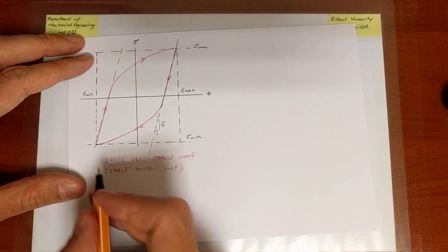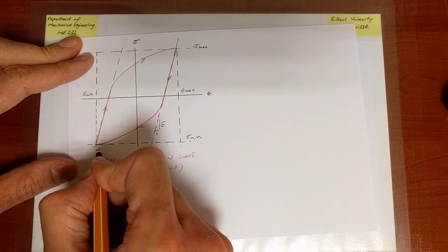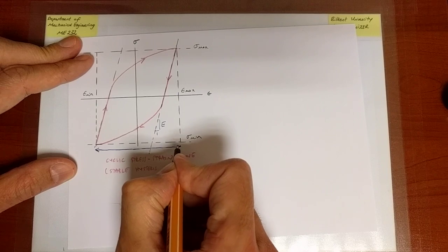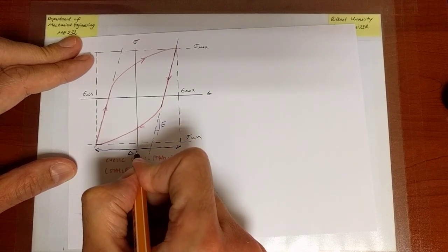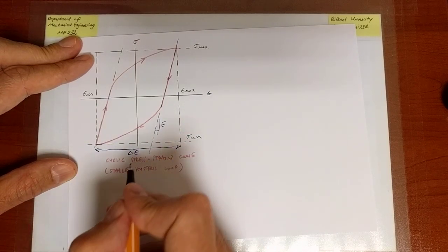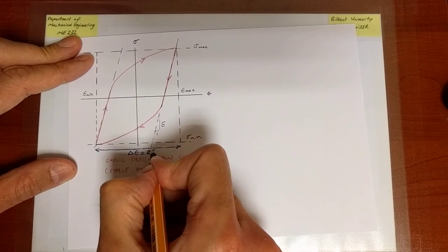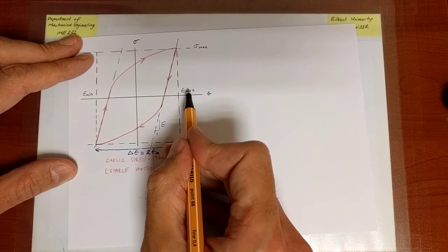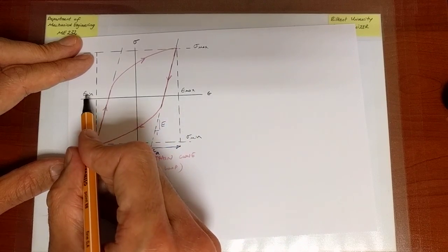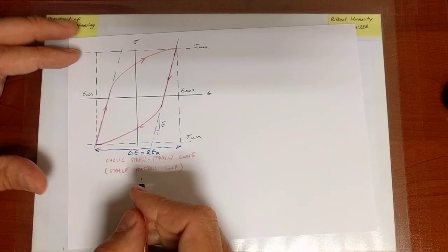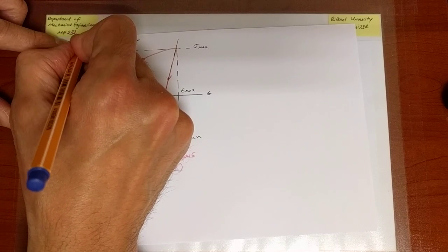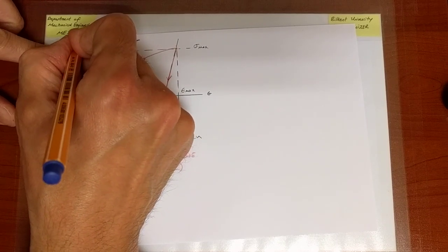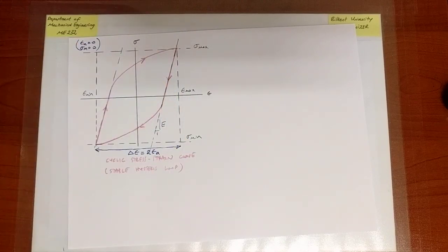So first of all, the strain goes between some max value and mean value. So therefore, this is the range of the strain, okay? And the range is always twice the amplitude. So here, this is plus epsilon A, and that is minus epsilon A in the present case, because the mean is equal to 0. Let's make a note of that here.